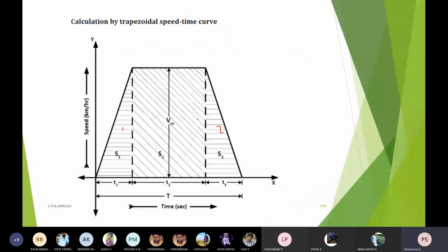Okay, so here we have seen that already. This is for the main line. I have just fitted the main line speed in the trapezoidal curve. This is a standard, fixed trapezoidal curve. I am assuming this as acceleration and free run, adding the coasting and the retardation. I am just making the rheostatic acceleration and acceleration, so I am taking completely this as acceleration, this as retardation or braking. I have just fitted the particular one in a trapezoid.